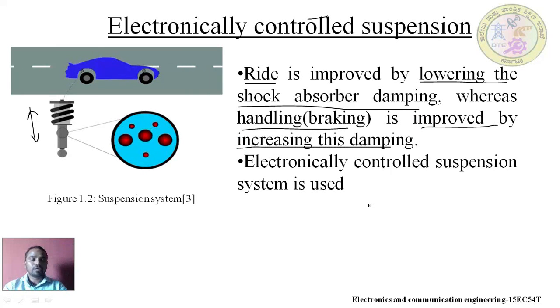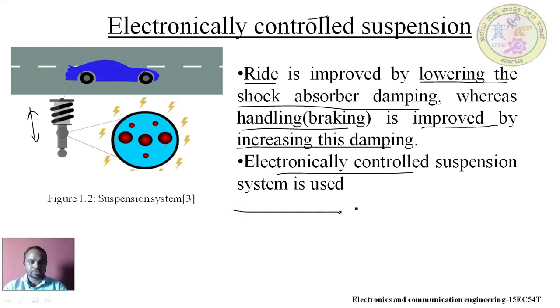In simple words, I can say that ride can be improved by lowering the shock absorber damping. Similarly, handling can be improved by increasing the damping of the shock absorber. Dear students, this can be achieved by an electronically controlled suspension system.